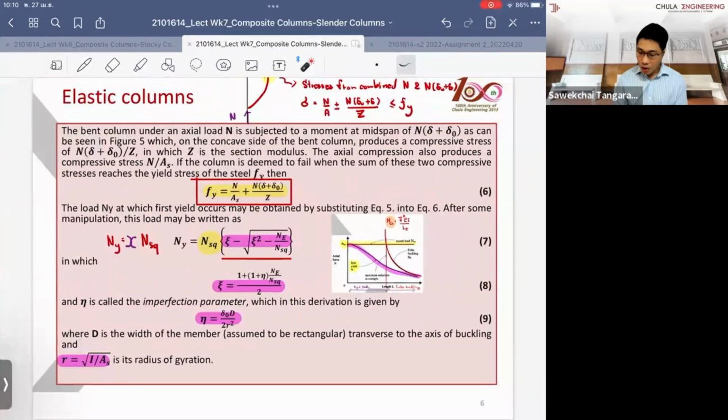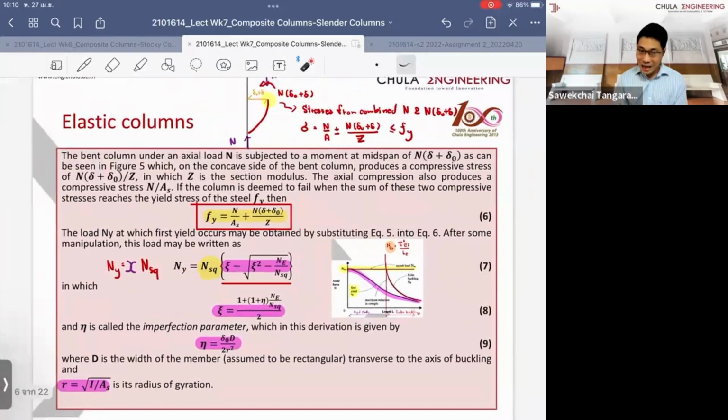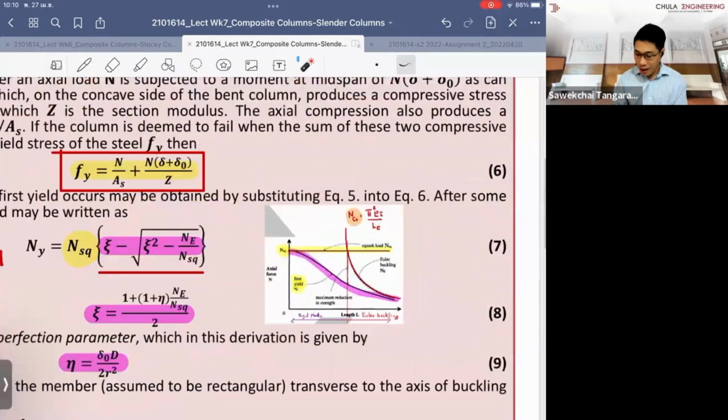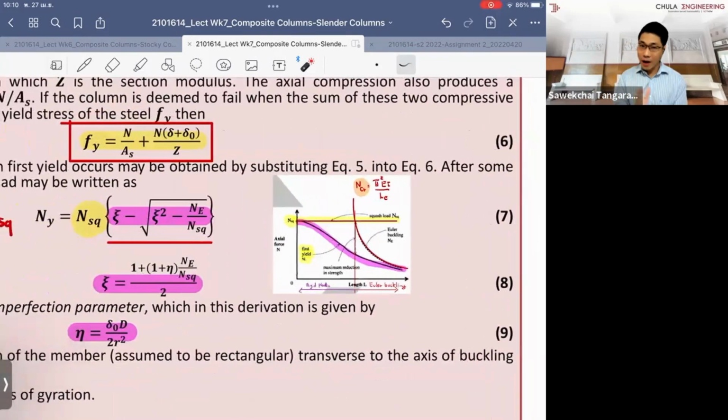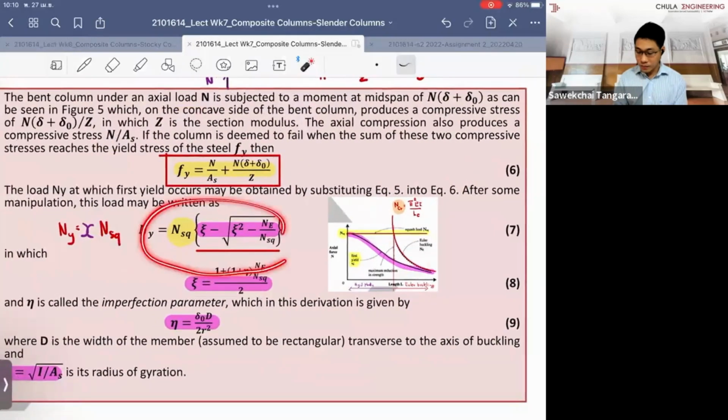And in this theoretical concept, we use it for the elastic analysis. So basically, the line that you have here, when you adjust them, is quite conservative because we don't allow them to develop the stress up to the full ultimate strength. So the stress diagram distributed to the cross section is still the triangle stress diagram. It doesn't form the full rigid plastic diagram. So if you use this formulation, it's too conservative, right?